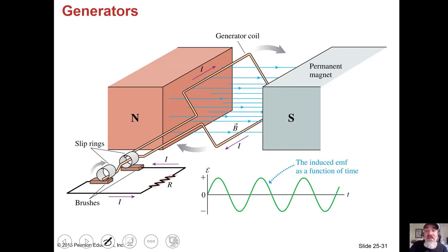See, the thing is, the force on the top, for example, is back this way. So if you get something rotating one direction, once you get to the other point, it wants to flip back the other way. This ring won't keep going. So the commutators down here actually change the direction that this thing is moving. That's what these are for.